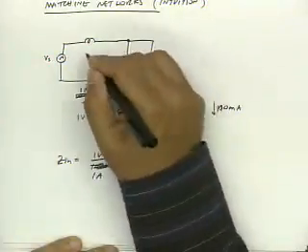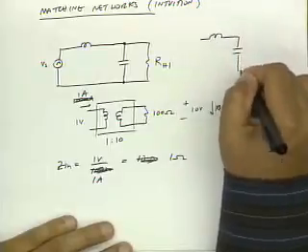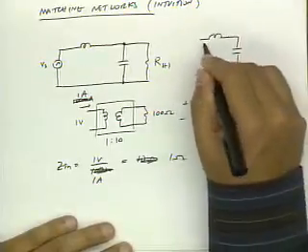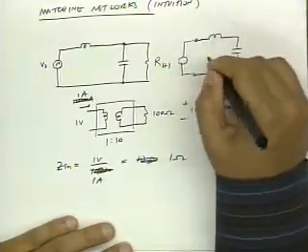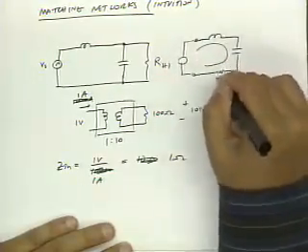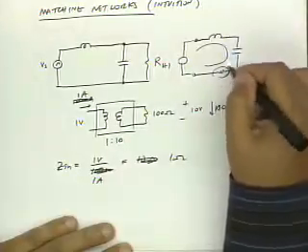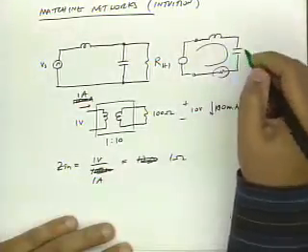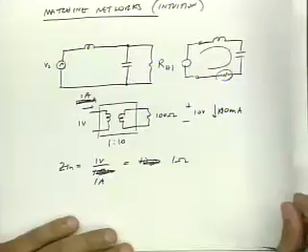So in a series circuit, the voltage across this resistance is going to be Q times less than the voltage across this reactance. So what I really want to do is take advantage of this Q multiplying property to make this circuit work.